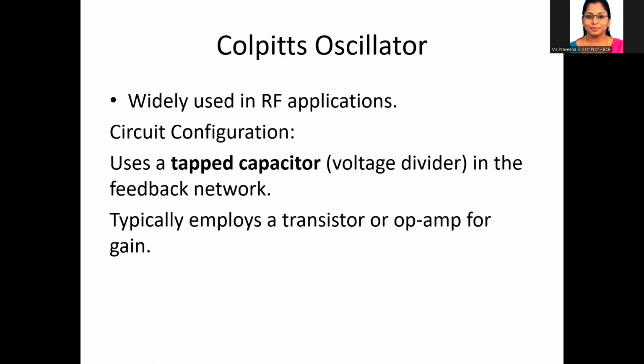The capacitor will be acting as a voltage divider, giving us a portion of the output signal back to the input that is in phase with the input signal. Both the capacitor and inductor together form a resonant tank circuit, and that will determine the oscillation frequency.